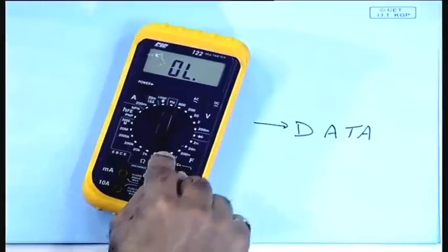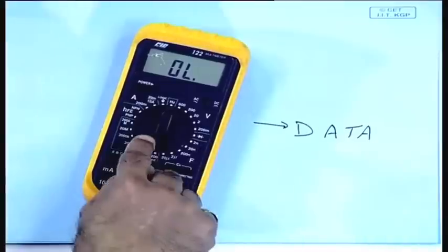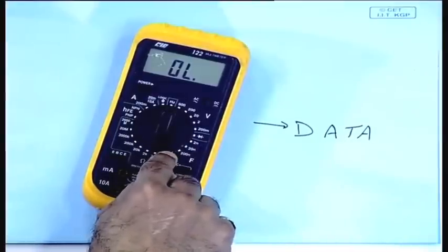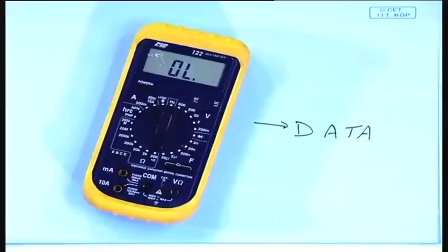The gauge and the method of measurement may introduce some variation, and that is what we call gauge error or repeatability error. So, if I repeat my readings, I will find there is some variation in it. This is due to the gauge itself. A single person making multiple measurements will end up with that variation, which is the measurement variation.